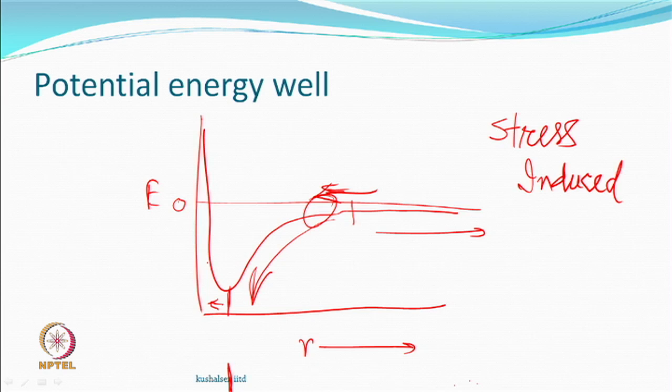They will finally themselves want to be there. But if the temperature is very low, then you say, well, do the drawing at a little higher temperature, allow mobility. That means you facilitate it, or then we had another thing called heat setting, thermally induced crystallization.